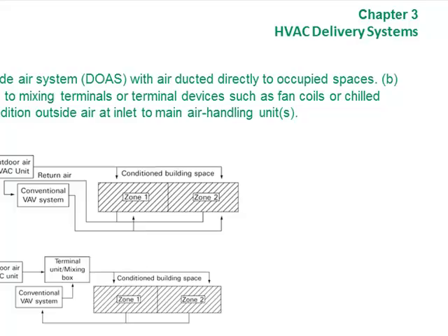What about a grocery store? What do you need in there? Something pretty cool. They can cool down a very big area. Yeah, it's usually cold in grocery stores. Say single zone. And you also probably have to control the humidity a lot because they got all those showers all over the vegetables. Okay, constant volume general reheat with multiple zones.